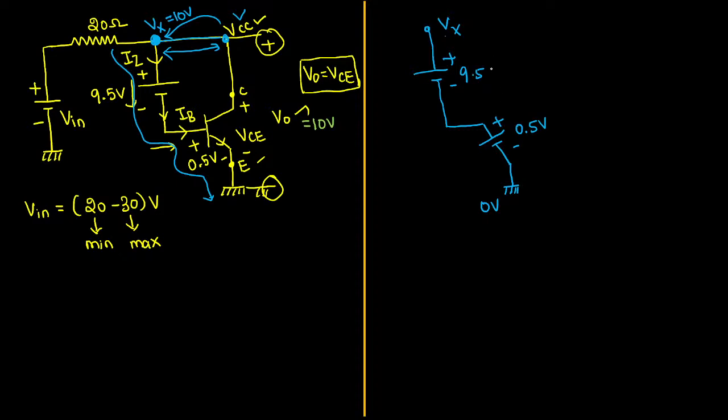So now let us take current always flows from higher potential point to lower potential point. First of all, these two elements, positive plate and positive plate are in the same direction. Like positive plate, it is placed at the top. Here also on the top only positive plate is placed. It means these two voltages are aiding each other.